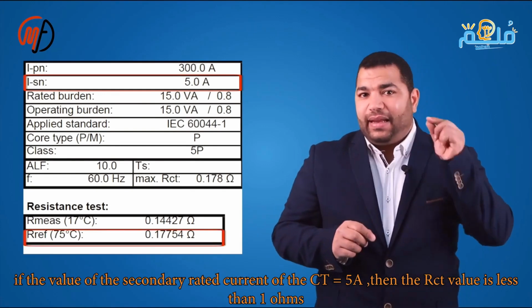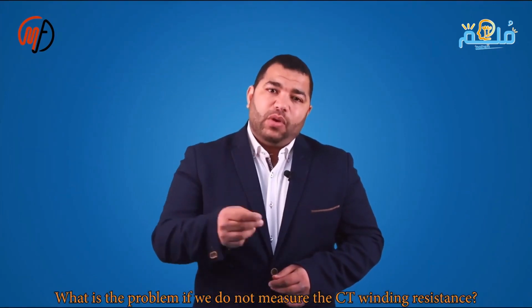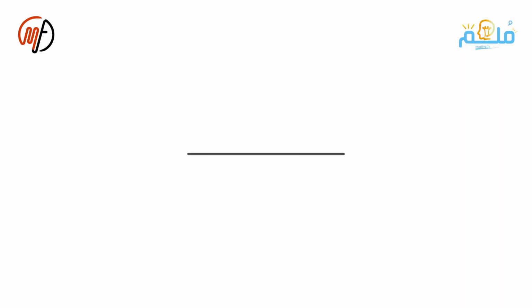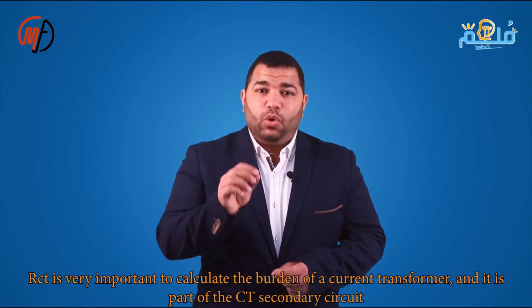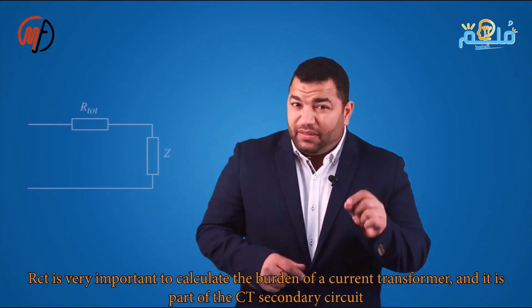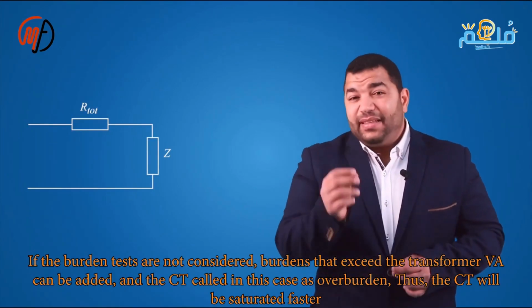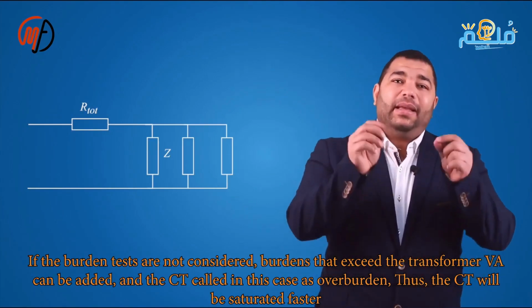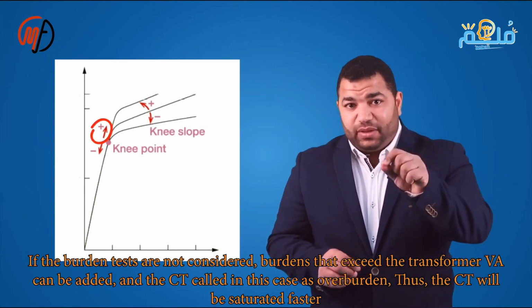First, the IR test. Second, the winding resistance test. Third, the CT ratio test. What's the problem if we don't measure it? The RCT is very important for calculating the burden on the current transformer, and it's part of the circuit. If it's not included in the burden test, then loads exceeding the CT's capacity will be added, making it seem like there's an overburden, which could cause the CT to reach the saturation point faster.